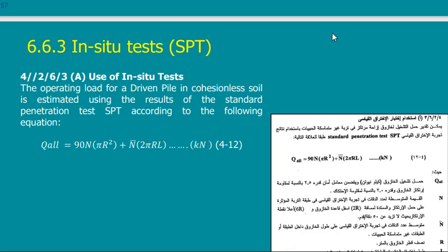In case I say that the pile can carry 200, and using my testing results, I found that it will not carry more than 150, then my design has to be changed to 150, not 200.